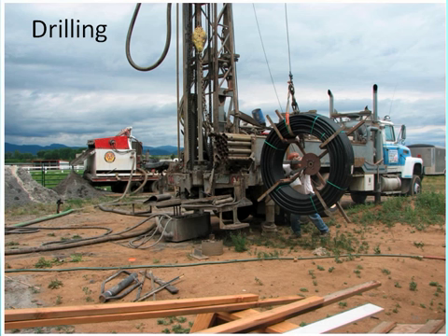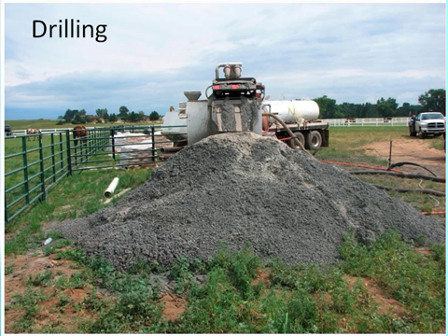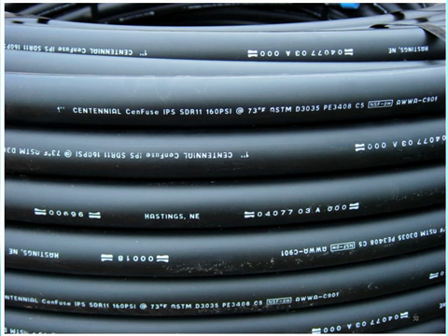Mud puppy is just a shaker table here. You see here the site's all nice and dry, and his mud pit box here is a lot smaller and a lot cleaner. He's about to load a loop here in a hole. But all the fluid and cuttings are going over here to this little shaker table here. Again, it's a mud puppy. And in these little piles, they're separating the drill cuttings out from the drilling fluid. So not only are they able to keep the site a lot cleaner, they're actually using significantly less water on a particular project here. This pile here represents about 8 boreholes that have been drilled 400 feet deep so far. But not all contractors have that, and it's not necessary, but certainly is an important thing.